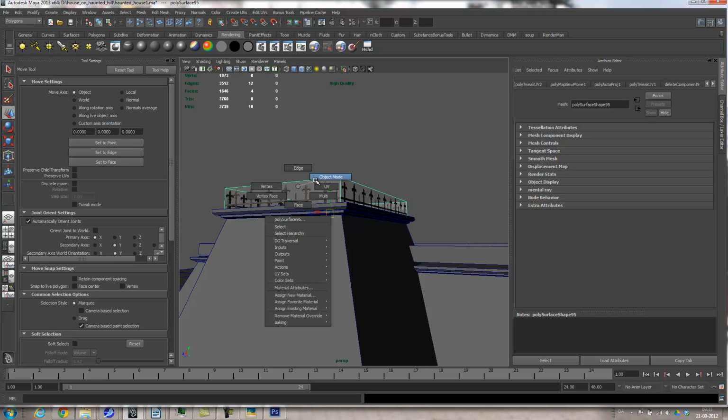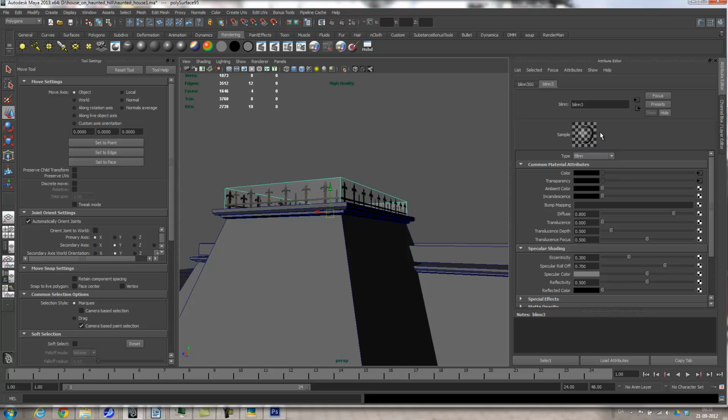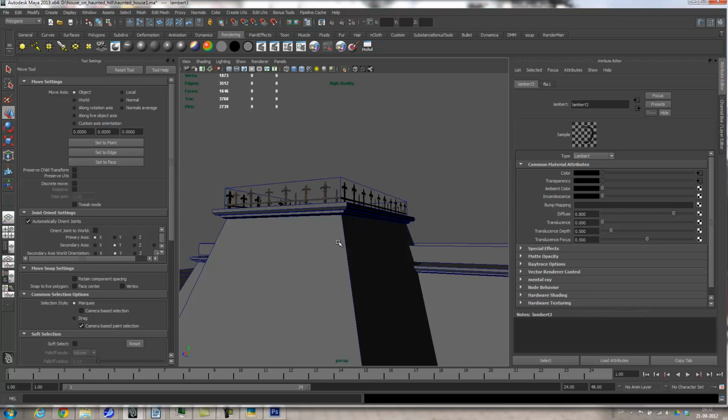That is by far the easiest. So just go change this to a Lambert, for instance. A Lambert is just a matte material, so it doesn't have any highlights. Another option I can use if I keep it at blend is to actually use the opacity, the inverse of the transparency, to control my specular, so that it will only have highlights where the model is.